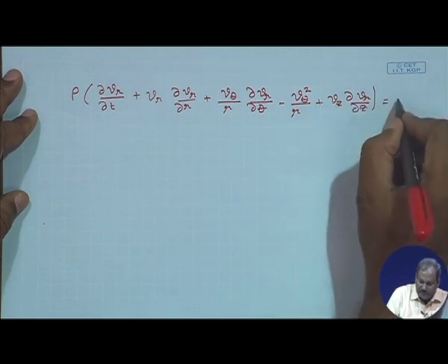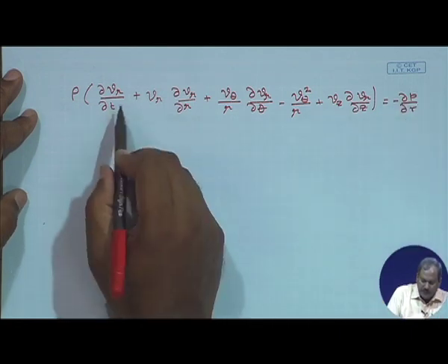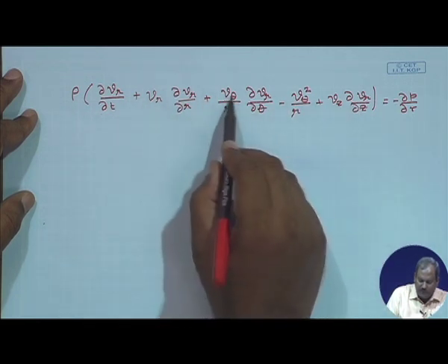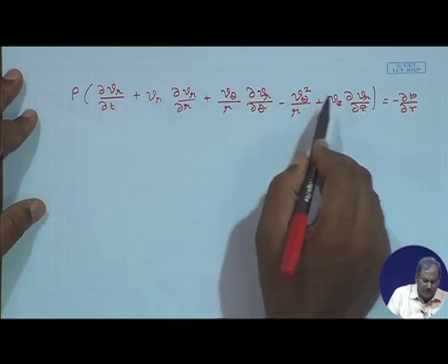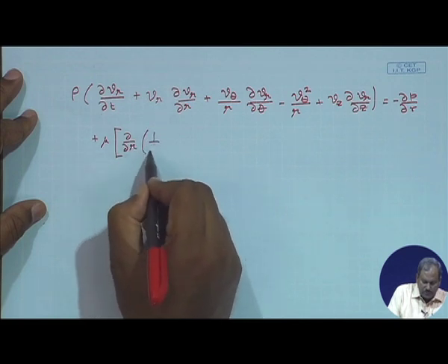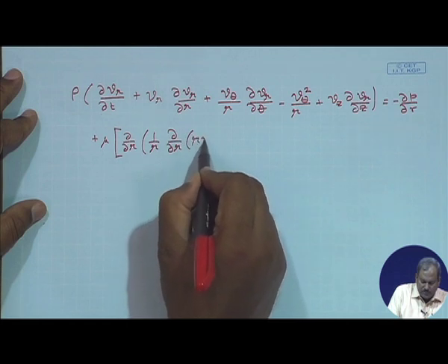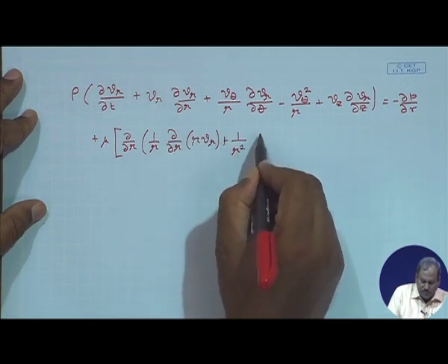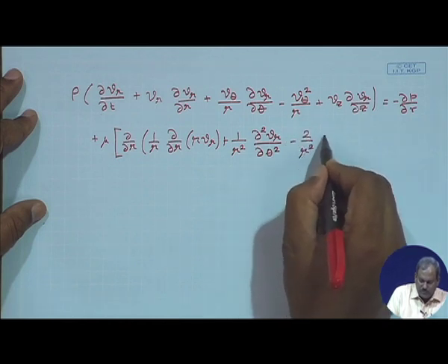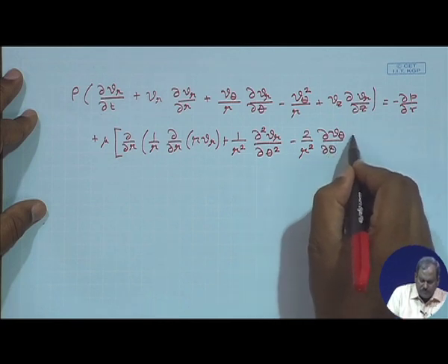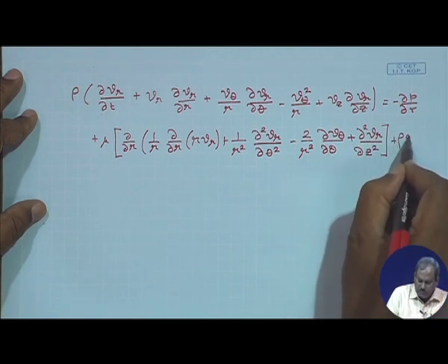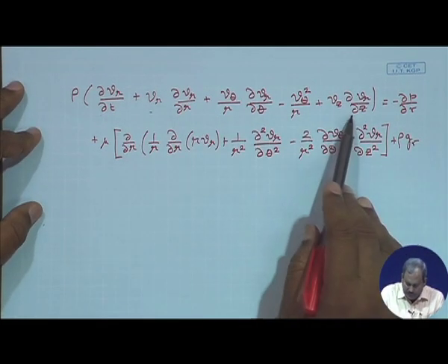So this is the entire left hand side. You can again identify the spatial term, and all these four terms, since they have velocity explicitly present in them, refer to the convective transport of momentum.